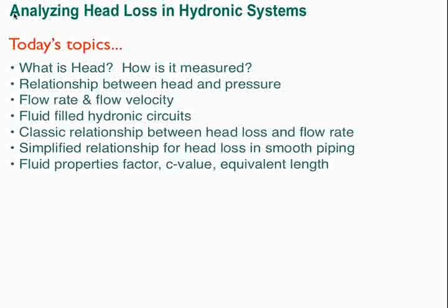We're going to talk about, in the process of simplifying the calculation of head loss, fluid properties, equivalent lengths. Again, these are essentially numbers that we have to gather up and process through an equation to calculate a head loss. And then we're going to look at a circuit head loss curve. Think about every hydronic circuit you've ever designed or ever will design. Every one of those circuits has a head loss curve. Just a matter of making some calculations to know what it is.